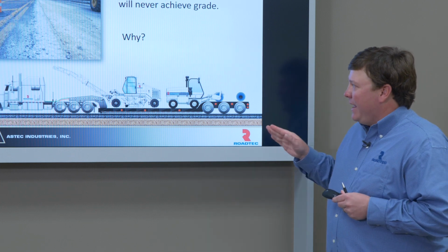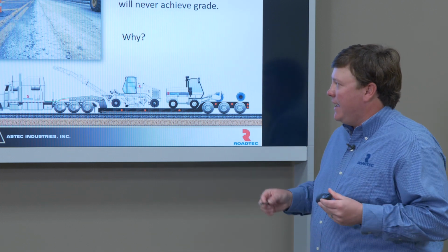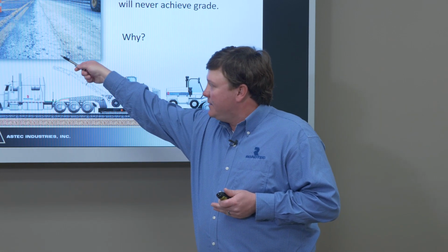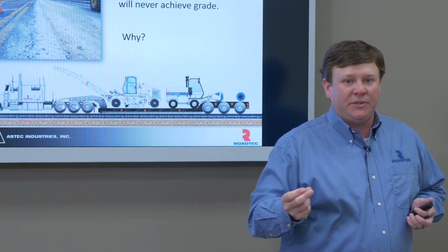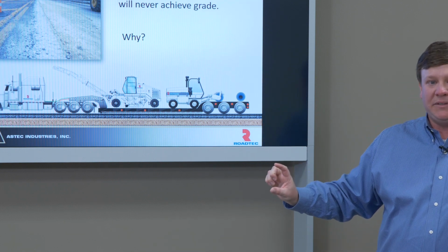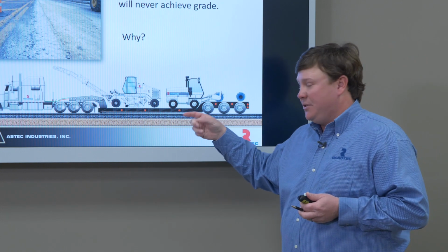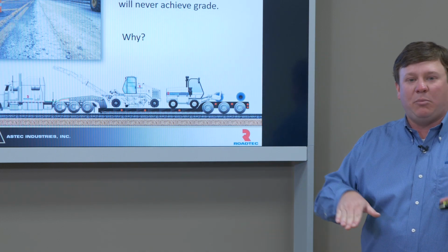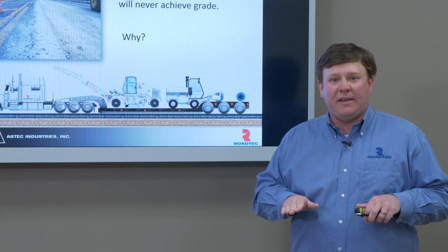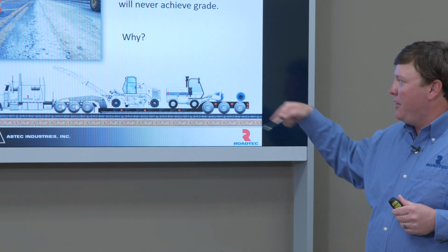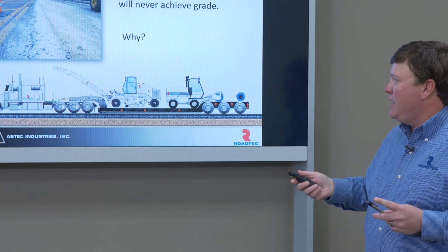Now, let's say one of our in-gate sensors or one of our sonic sensors rolls over these rocks here. Well, to the sensor, that is the surface. That's what you told it was the surface. It's not the actual surface, it's just debris. So if we don't clear that obstruction, now we don't get the proper grade that we were seeking when we began. So all this debris is going to throw off our grade. We have to keep it clean.